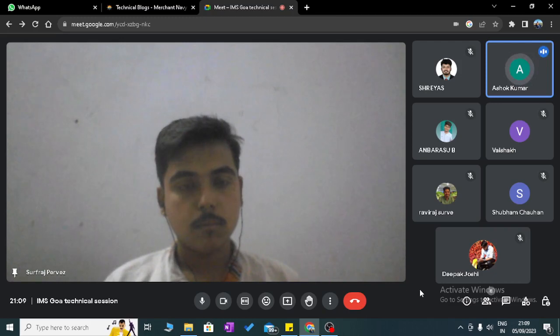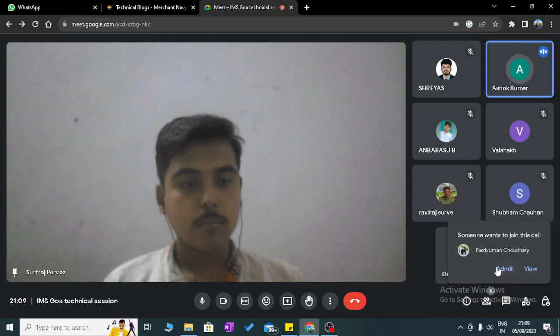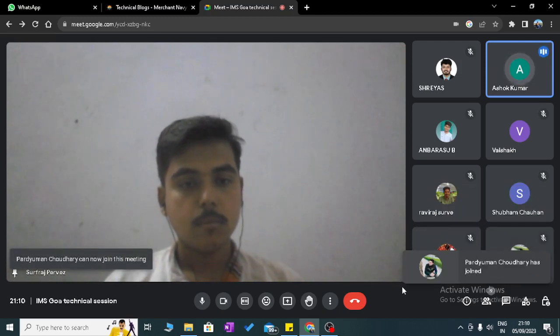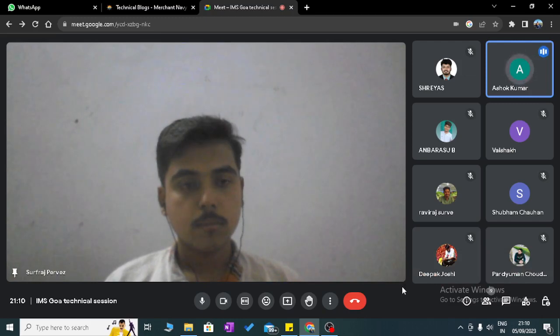So a vacuum pressure is created in the eye of the impeller. So a suction of fluid is created in the eye of the impeller, and the fluid flows circumferentially outward toward the discharge side along the casing. The area of the casing gradually increases toward the discharge side, so as the area increases, velocity decreases according to the equation of continuity.